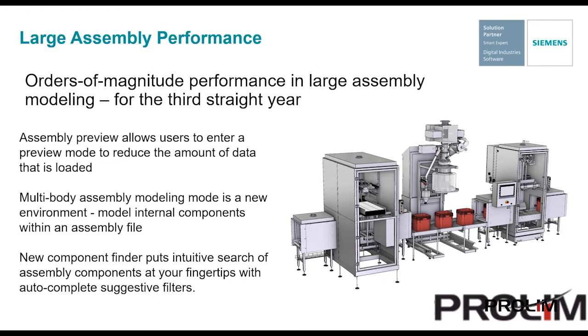So Siemens has been investing heavily in the large assembly modeling performance realm, and it shows. For the third straight year, they have achieved orders of magnitude performance improvement, and it was already pretty fast before. But Solid Edge's new capabilities make it even faster. The new assembly preview mode allows you to enter the preview mode in order to reduce the amount of data that is loaded. You can view, rotate, pan, and even change configurations prior to loading the full assembly. It switches on based on the size of the assembly and opens in seconds. So let's see a quick example of this real quick.